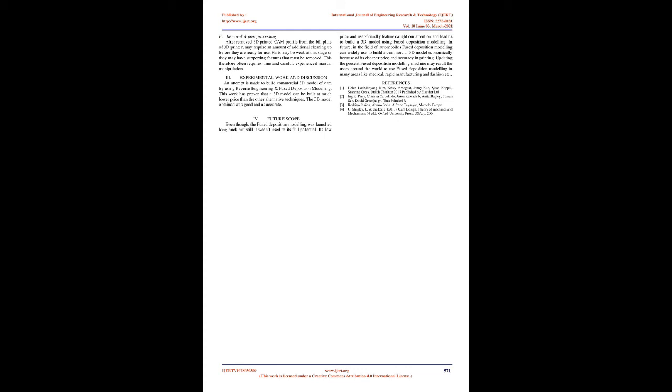Printing of the first object layer, the one in contact with the printer bed, has some peculiarities, like problems of object adherence to the bed, roughness, and smooth deposition of the first amounts of filament. The slicer can automatically add some detachable structures to minimize these problems. Usual types of these base structures are a skirt, a single band around the base of the object without touching it; a brim, several lines of filament around the base of the object, each one a bit farther from it until touching it, but not under it; and rafts, several layers of material that form a detachable base, with the object printed over it.